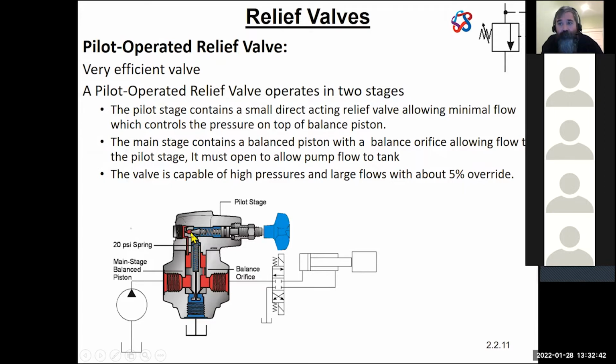A little bit of fluid. But the fluid moving past this poppet is more than the fluid that can move through this orifice. So I've let a bunch of fluid go quicker than I can let the fluid go in, and the fluid's virtually incompressible. So what happens is that the pressure up on this top side of the chamber drops, okay?